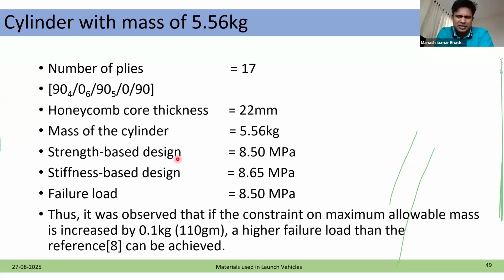So with this, I am concluding my talk on this topic, that I have covered the various material and the challenges, particularly with respect to managing steel. Because of its high strength, it is prone to fracture, and how the fracture assessment is carried out. The three parameter fracture model, which we are currently using for assessing the fracture of the various metallic motor cases. And the developments, how we are able to couple the FE analysis with the fracture assessment in the three parameter fracture model.